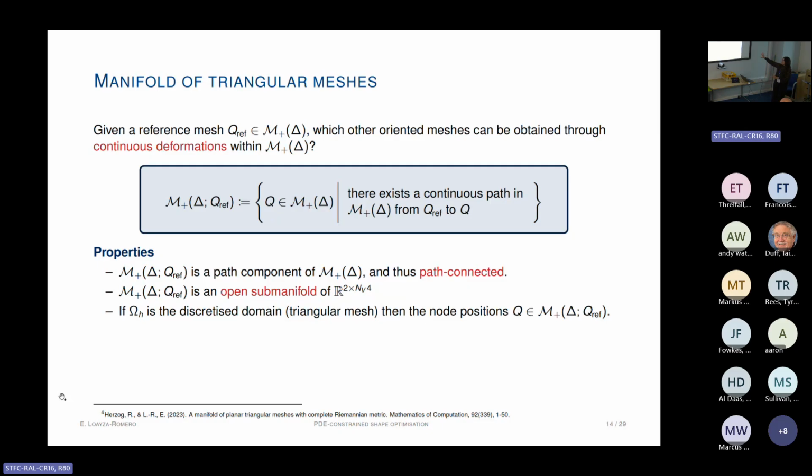If you think about this very particular case of triangular meshes, that means that no matter how my mesh looks, and no matter how my initial deformation field looks, if I am able to follow geodesics along this, I'm never going to destroy my meshes. And not only are they not going to be destroyed, but they are also going to have good quality, because of this energy minimization property that the geodesics have.